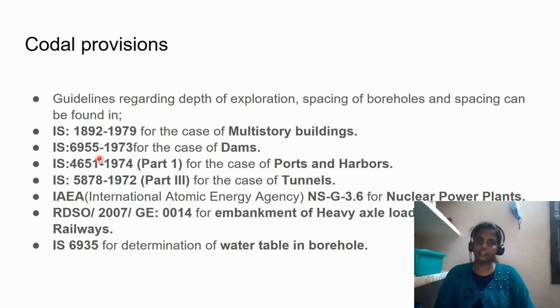The guideline can tell you you need four boreholes to collect samples from the site. But if the soil samples from the four boreholes are all going to be entirely different, then you have to go for a fifth borehole. It doesn't mean that you shouldn't go for a fifth borehole, since the guideline has set only four.